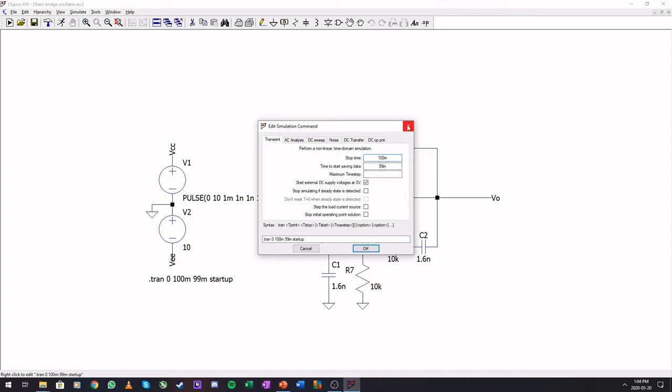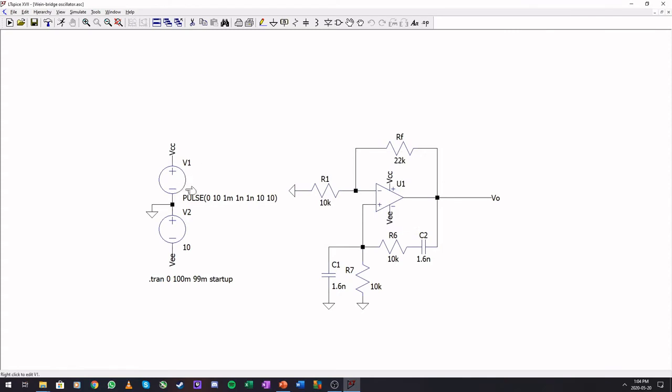With this simulation, initially I had some issues, so this top supply I just made a pulse to cause some instability in our system so that it will actually start oscillating and not just provide a stable output, because there is no noise in a simulation. In any other videos I do, I'm not going to repeat that I pulse the input. You're just going to see it happen.